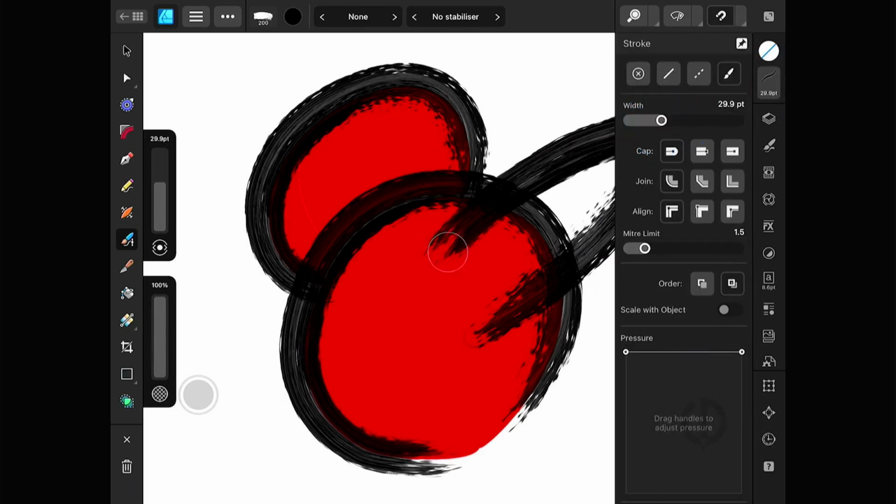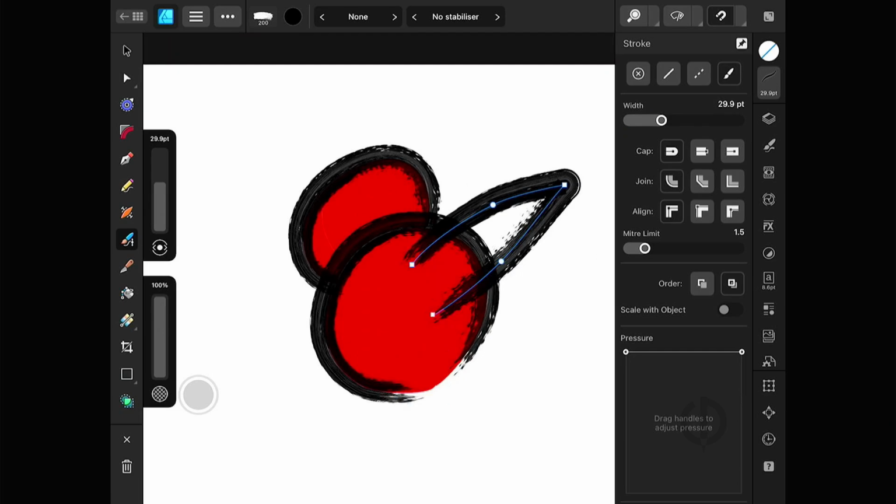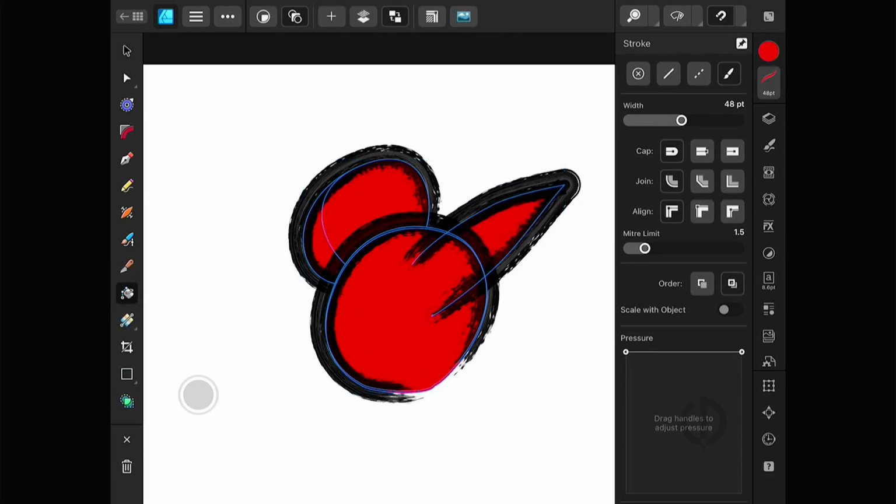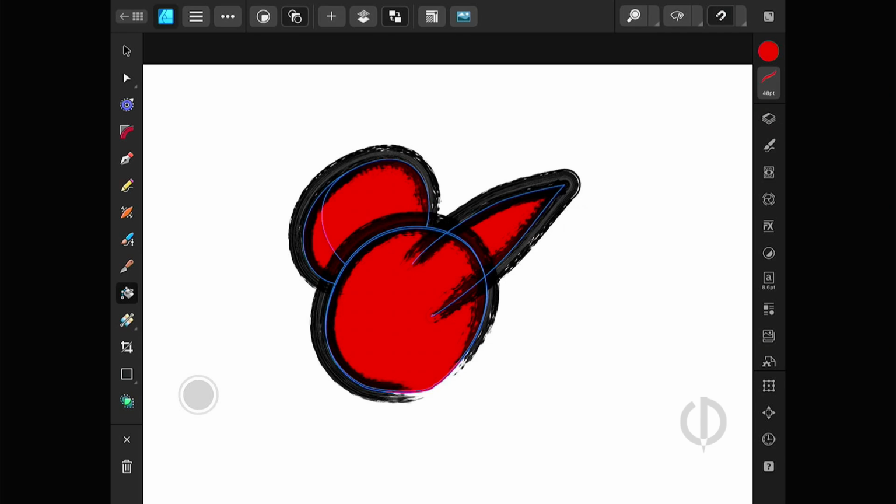When you use the Vector Flood Fill tool, you have to select or group all the objects to apply color. Alternatively, the easiest way is to draw lines that touch as much as possible and then color in the Pixel Persona instead. Both vector and raster methods depend on the needs of your work. You'll have to choose the method that works best for your project.